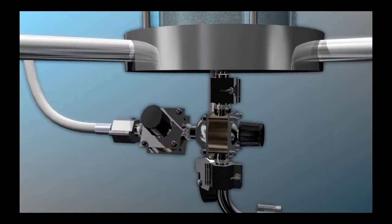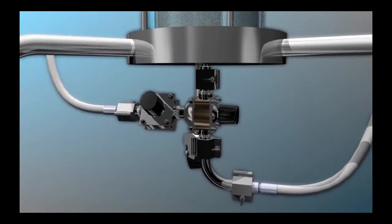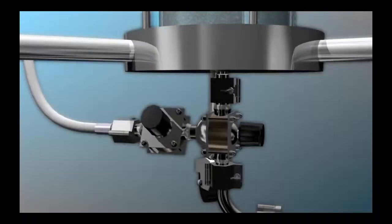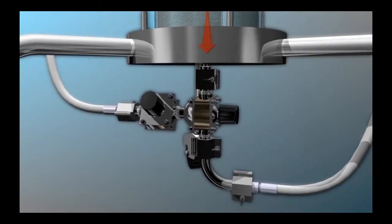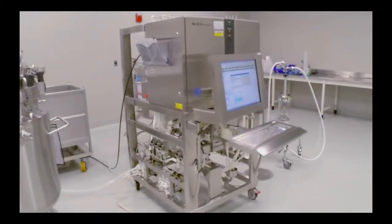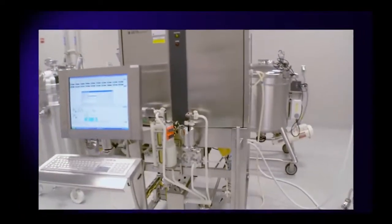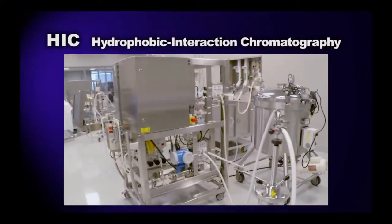The UV optical density sensor, which measures protein concentration, indicates when product begins eluting from the column. At this point, outlet valves are switched to allow flow of the eluate, the product stream, to a collection vessel. When the UV sensor indicates that all of the GFP has come off of the chromatography resin, the outlet valves are switched to waste. When all of the eluate has been collected and pooled, the anion exchange chromatography step is finished, and it's time for HIC,